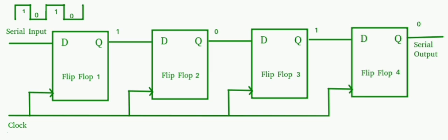Power dissipation in CMOS is of two types. Static, which is present during logic 1 or logic 0. Dynamic, which is present during logic level transition. Dynamic power dissipation equals C F VDD squared, where C is capacitance, F is frequency, and VDD is the supply voltage.